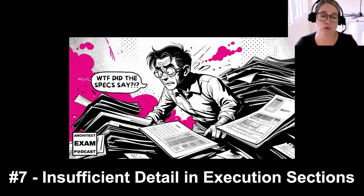So the solution, and the way to avoid this, is to include step-by-step procedures for critical systems, especially those related to the building's exterior and the building envelope, especially with regards to life safety or anything that would have extreme consequences when it comes to a failure of executing properly.